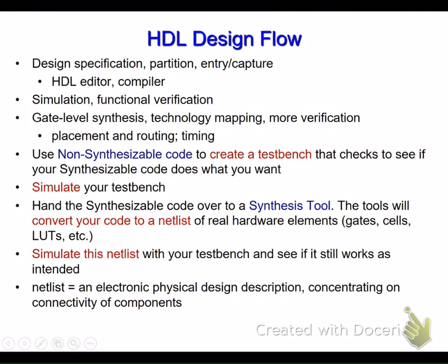So with this HDL design flow, at the very beginning you will write your code, then compile it and see if you have any errors. Then you will begin some simulation, and after that you can do synthesis, or you can skip the simulation, do the synthesis, and then do the simulation after the synthesis. Of course, this will be non-synthesizable code. You can create a test bench to test your design, and then simulate using your test bench.